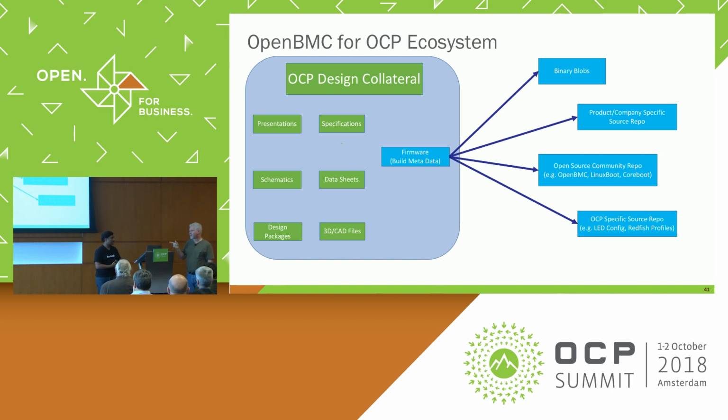One thing I want to add on to that, Sai mentioned that somebody quoted you like 6 months to do a special BMC for you. So one of the goals here with OpenBMC is it's a data-driven model. If you're doing a cookie cutter kind of step and repeat operation for different servers, that's a configuration change. You're not adding code unless there's a driver change or you're adding a new device. But it'll be a configuration change, and my goal would be for that to be, I'll say, a 1 hour job. Just change the configuration tables, the topology, should be a configuration change.